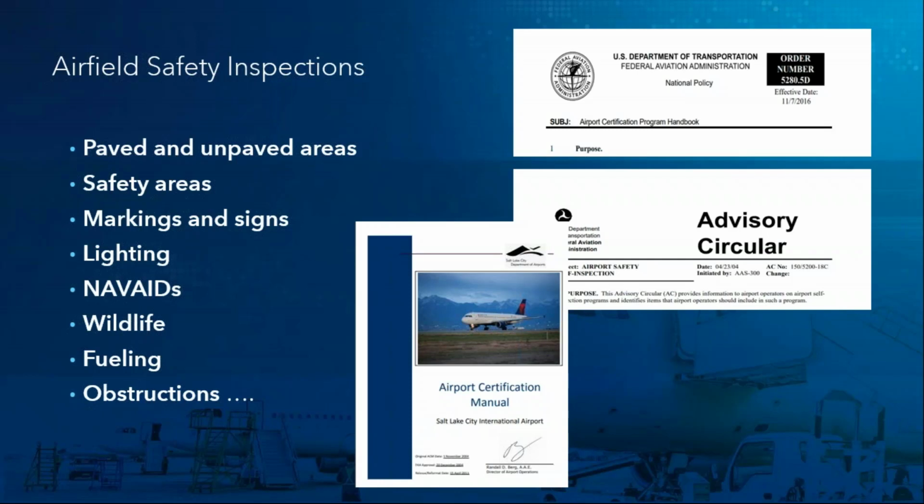They need to be able to demonstrate that they have qualified personnel to do the inspections, and that those personnel have been trained, and a reporting system to ensure prompt correction. So in other words, the ability to generate work orders and the ability to document completed work. And then finally, to maintain those inspection records and the corrective actions for a 12-month period.